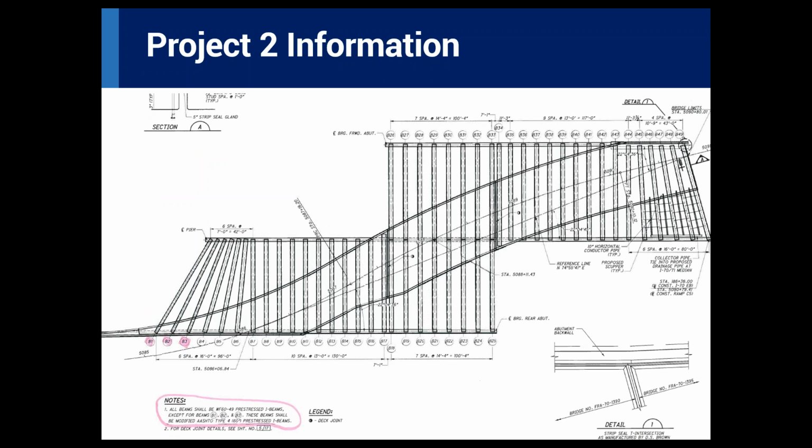So the second project is, as you can see over here, the bridge deck is poured through this deck outline. Basically, these are Ohio pre-stress beam sections, wide flange 60 beam, and some of the outer girders B1, B2, B3 actually have smaller sections.